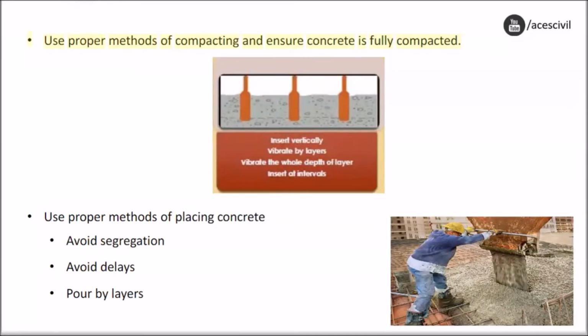Use proper methods of compacting and ensure concrete is fully compacted. Use proper methods of placing concrete. Avoid segregation. Avoid delays. Pour by layers.